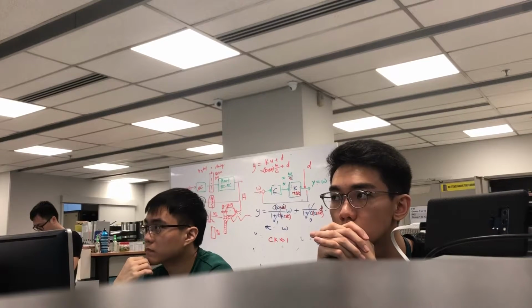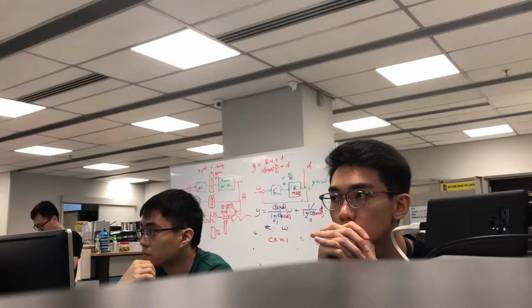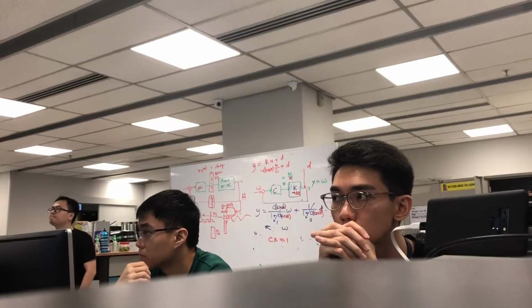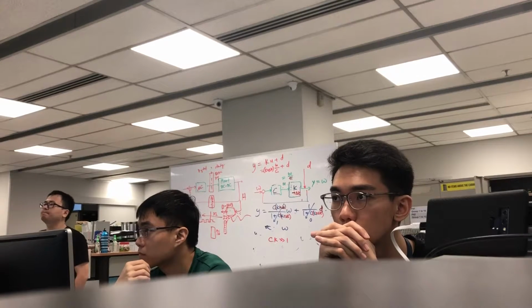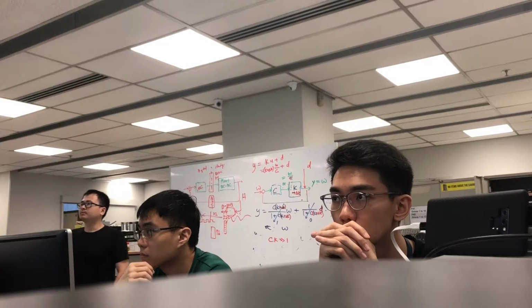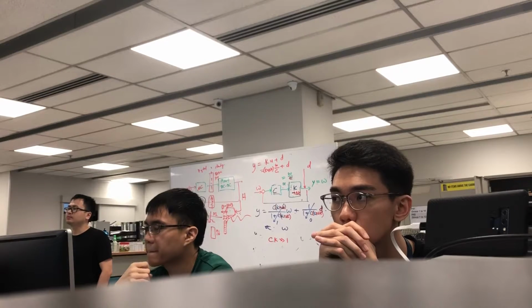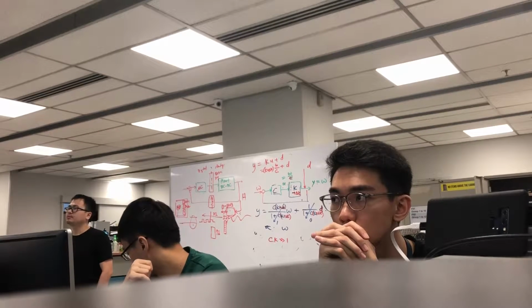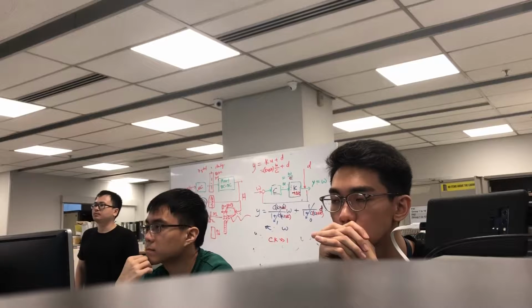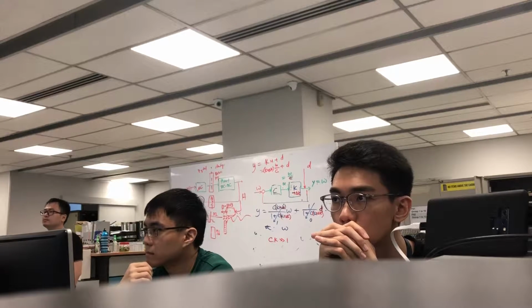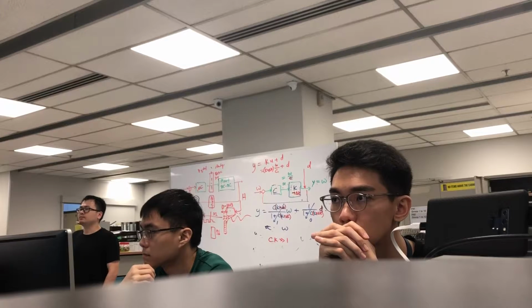It sets up all the necessary registers, either to generate PWM on pin 3 or P11, or when you use this, it will generate PWM signals from pin 9 and pin 10. And this sets the frequency. This one is fixed at 7 kilohertz. And then we just keep on saying generate this PWM and this, and repeat.